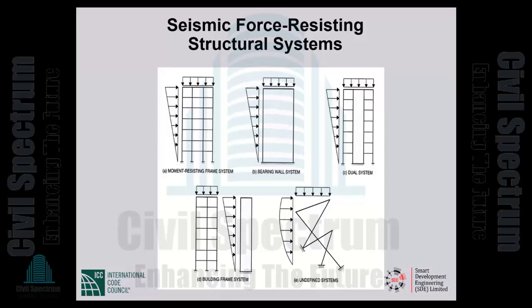In a building frame system, we separate gravity resistance from lateral resistance. We have to have essentially complete frames, essentially complete moment frames carrying substantially all the gravity. The words essentially and substantially are both important. I didn't just throw them in. The frame has to be essentially complete, not necessarily 100.00% complete.